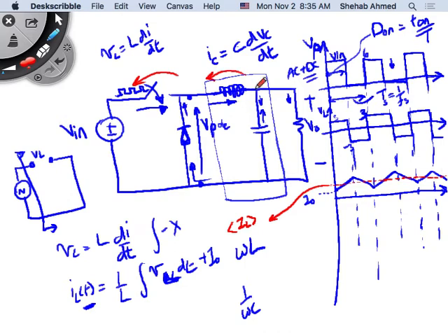We have a node here now with current coming through to that node, right? This current is now going to be pushed into the capacitor to charge it, and into the load to feed it, right? This current is this blue waveform. This blue waveform, what is it again? Is it pure DC, or is it AC plus DC? It's AC plus DC, right? So this blue waveform has an AC plus DC component.